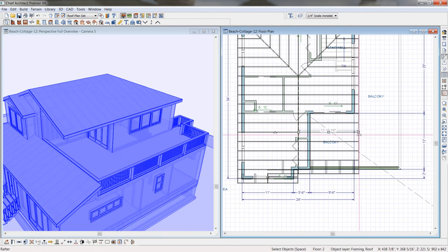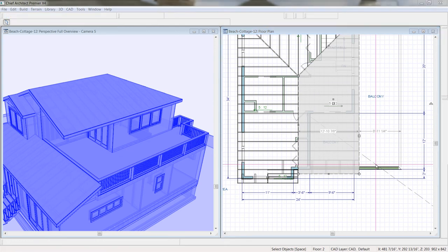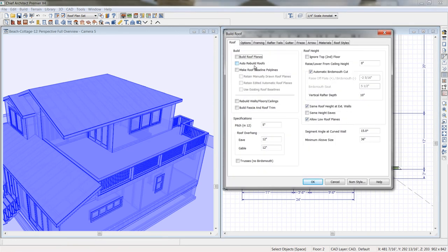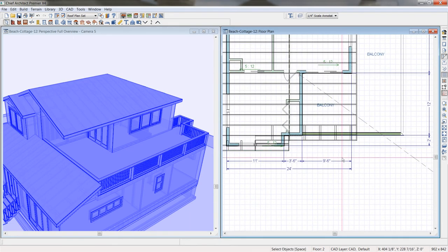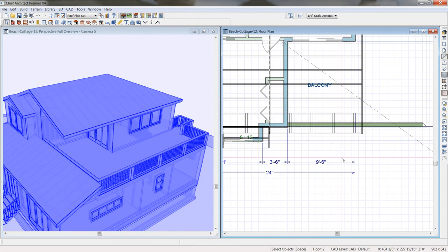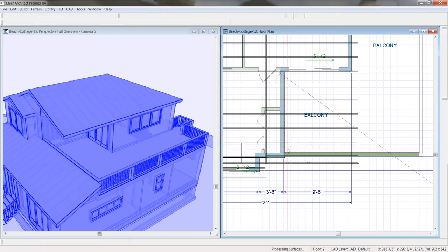And the first thing I'm going to do, this is the roof plane that we have selected. I'm going to make sure that our automatic roof is not on, because if I make changes to that, it'll instantly update it. So if we zoom in to this section, I'm going to take these lookouts and highlight each one of those, and then press the delete key and remove those.